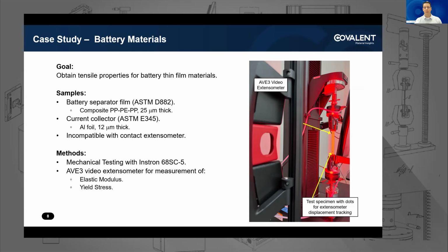We did our testing on the Instron 68SC5 using the AVE3. And here, the key things that the AVE3 provides to us are the material properties that depend on accurate measurement of low strains. Specifically the elastic modulus and the yield stress, and that's what I'm going to highlight.